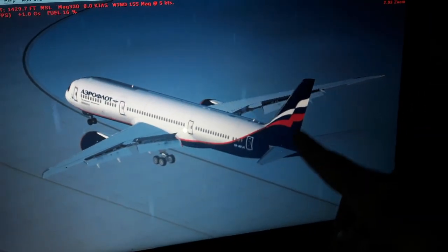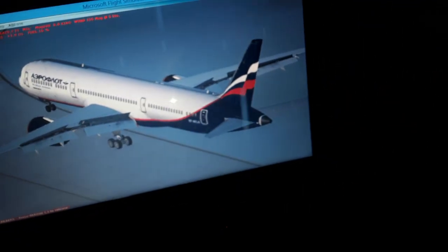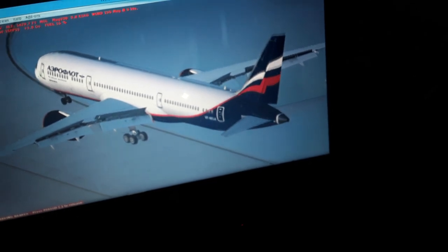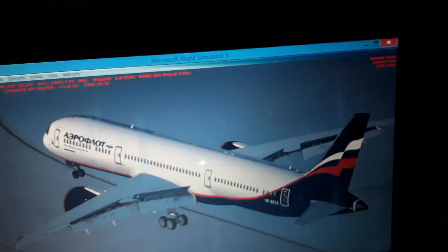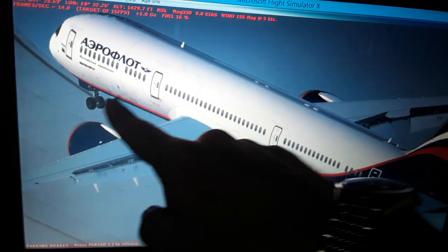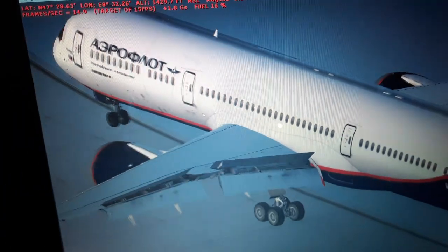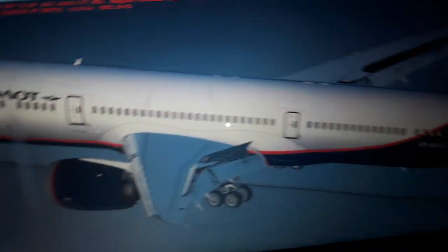Also above 45 knots or 72 kilometers an hour, the rudder becomes aerodynamically effective, so the computer will limit automatically. You don't need to do anything when you press the rudder pedals: from 76 degrees left and right down to 7.6 degrees for the forward nozzles, as you can see.